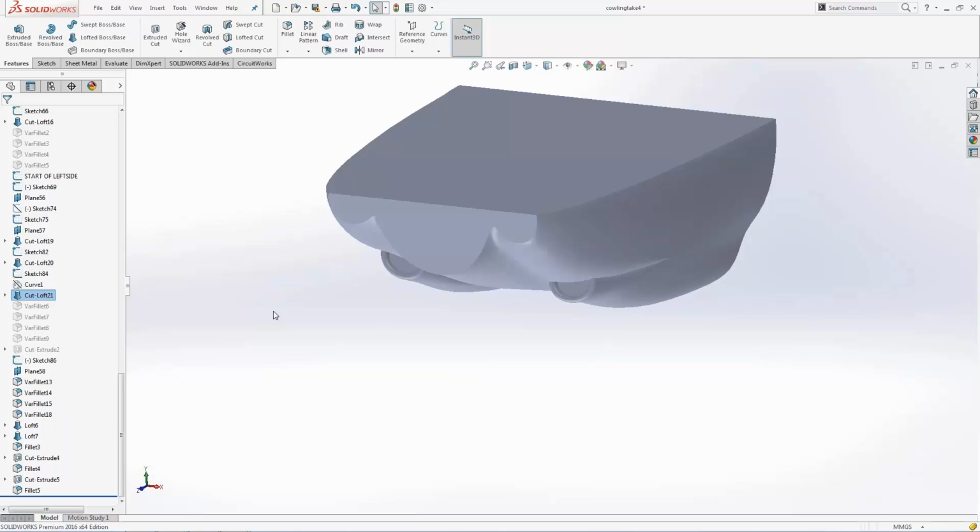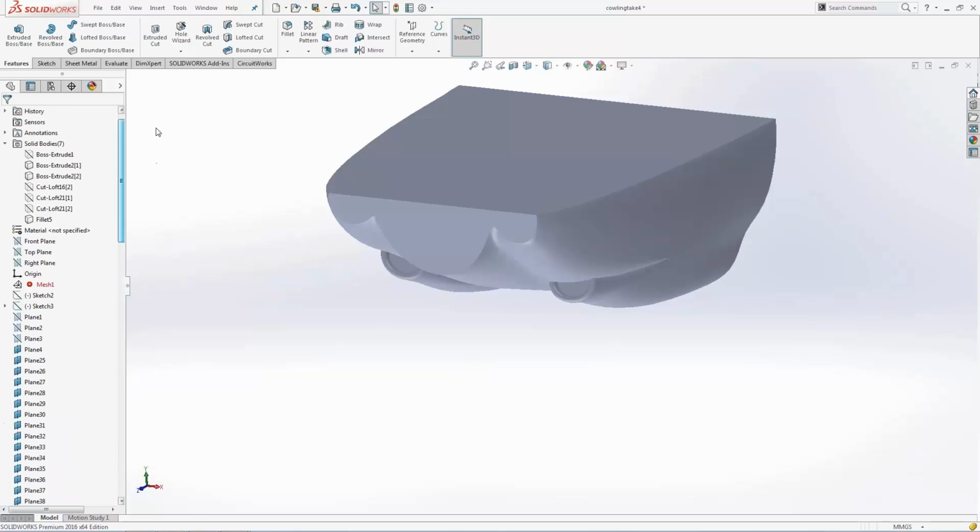When we have merge selected, it thinks this is cut out of one big chunk of metal, if you will. So by unselecting merge, it's going to create these independent bodies that you saw up here. And now I have this full control where I can turn on and off what I need on a whim. So this was one option that we looked at. This was the fourth intake option, and I think we ended up with about 6 of these, but they were all created using this method.